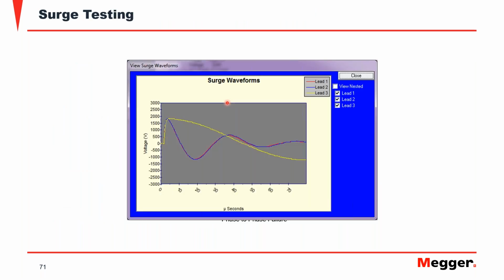Now, you can have different, let's say, waveforms that you will see. Sometimes you will see something like this. Now, always remember the equation. I should have put it here, but I didn't. The equation of the frequency. There are parameters in the equation of the frequency that are the inductance, but there's also the resistance. Sometimes when you have a resistance that's too big, then you will have a frequency that's very low. And when the frequency is very low, then you have an elongation of this waveform, because remember that this is time here, and the frequency and time, they have an inverse relationship.